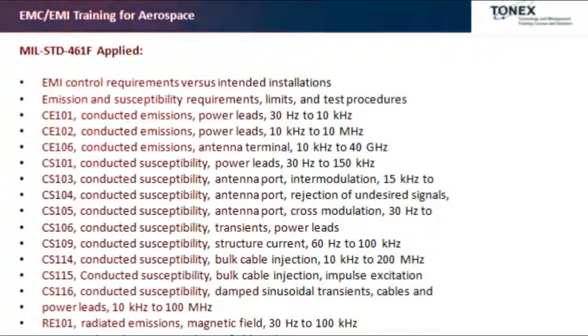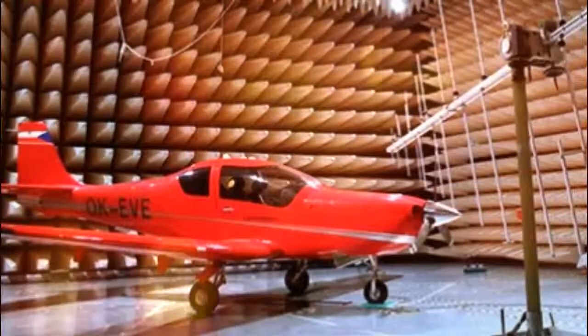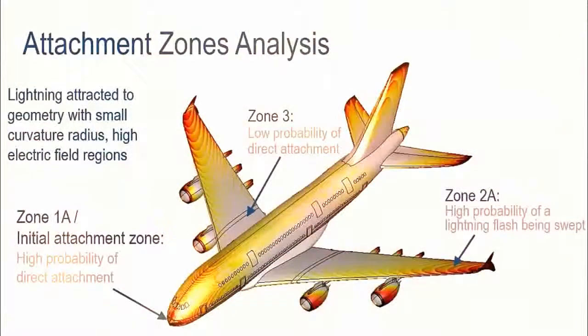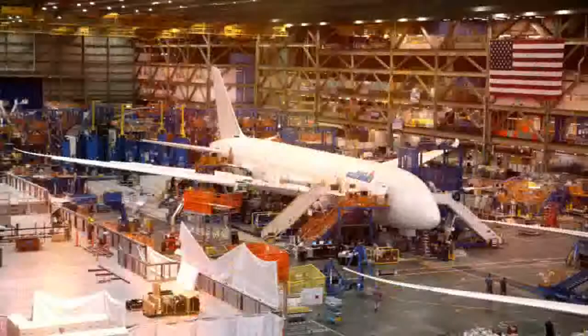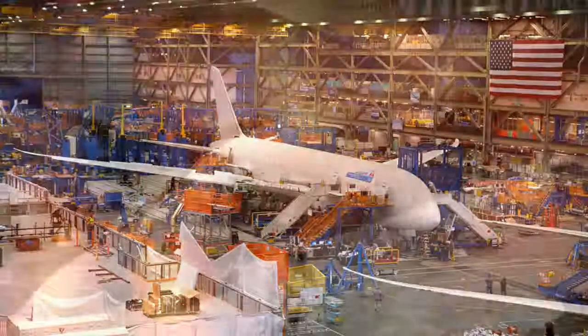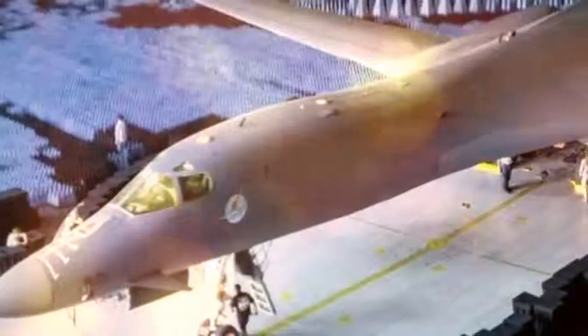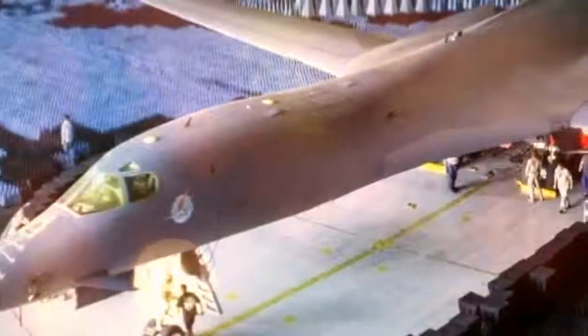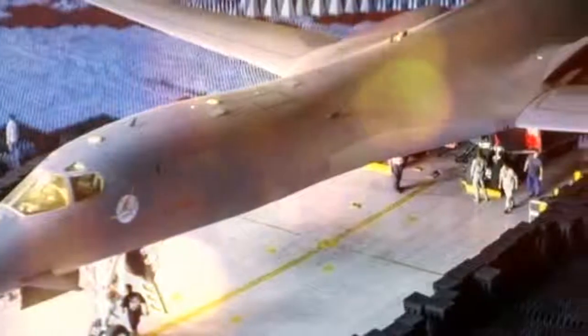MIL-STD-461F Applied. EMI control requirements versus intended installations. Emission and susceptibility requirements, limits, and test procedures. CE101, conducted emissions, power leads, 30 Hz to 10 kHz. CE102, conducted emissions, power leads, 10 kHz to 10 MHz.